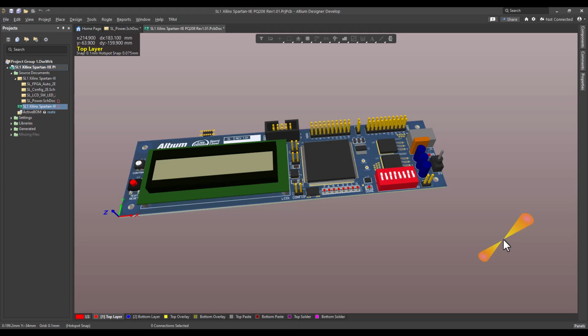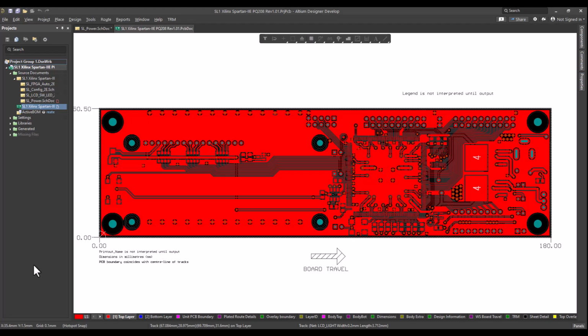We will bring current from this point somewhere to that point, assign some watts to the components, and perform an electrothermal calculation. This is the 2D view seen from the top layer. Our intention is to bring current from this point somewhere here using the 5-volt net. And there are several methods to assign amps to pins and pads.